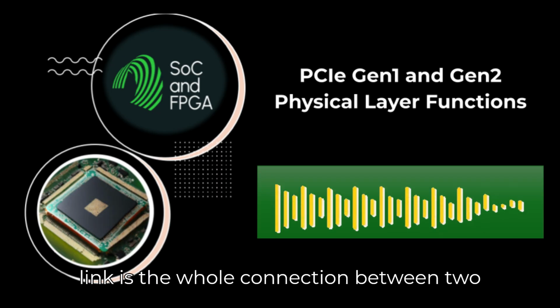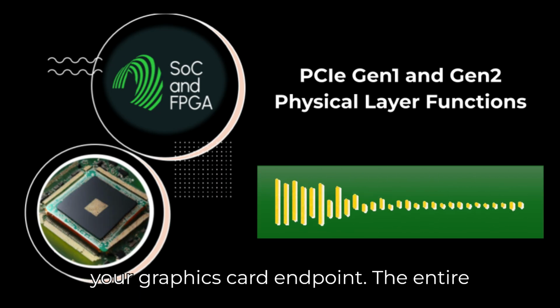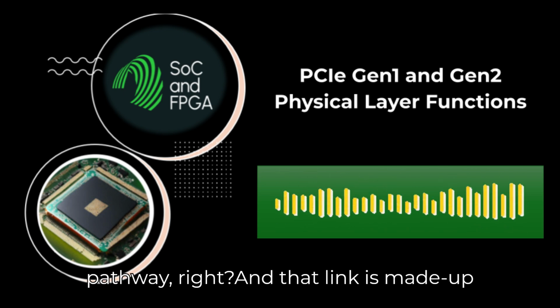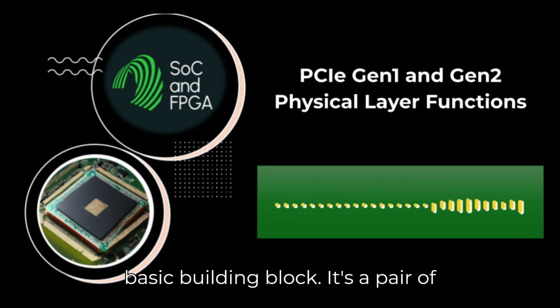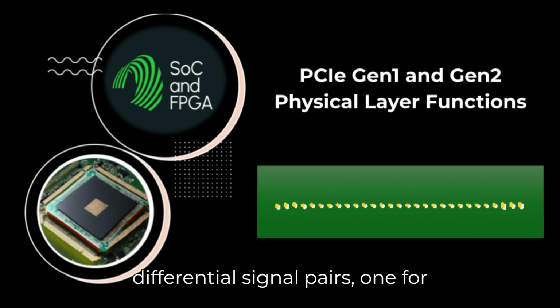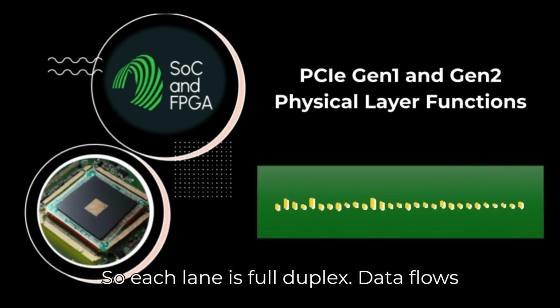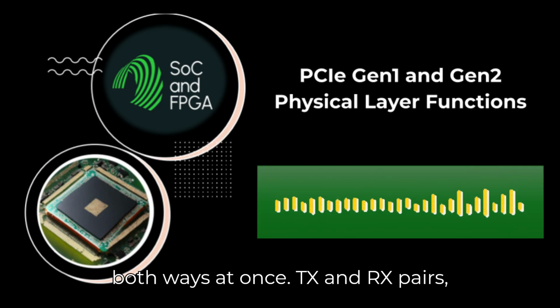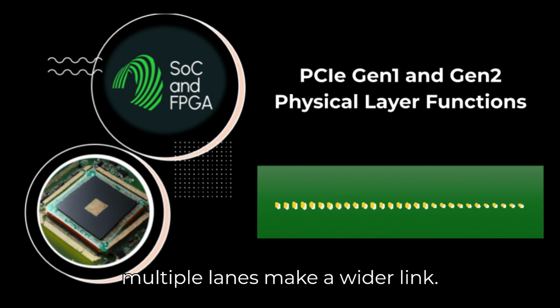Okay, a link is the whole connection between 2 points, say your CPU's root complex and your graphics card endpoint. The entire pathway. Right, and that link is made up of one or more lanes. A lane is the basic building block. It's a pair of differential signal pairs, one for transmitting, TX, one for receiving, RX. So each lane is full duplex, data flows both ways at once. TX and RX pairs, differential signaling. Yeah, and multiple lanes make a wider link.